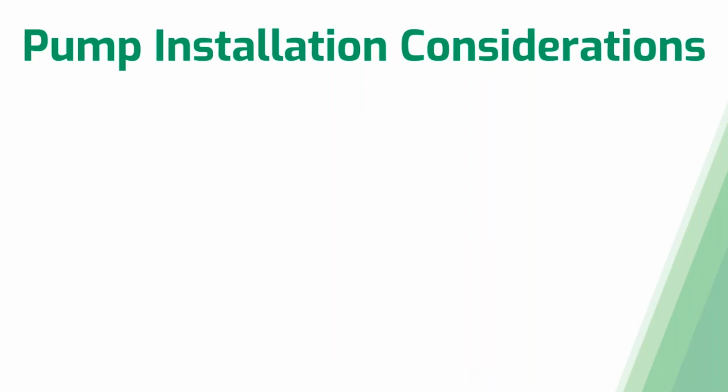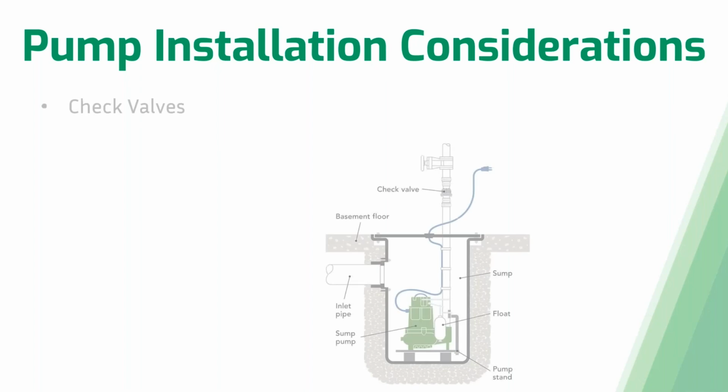So now let's talk about some pump installation considerations. First off, you're typically always going to want to use a check valve with your pump station. That is to protect the pump from any water that may want to come back down into your pit after that pump turns off. That check valve is going to close off that water from coming back in above the check valve. It's typically going to have some sort of swing plate that will close shut and thus keep that